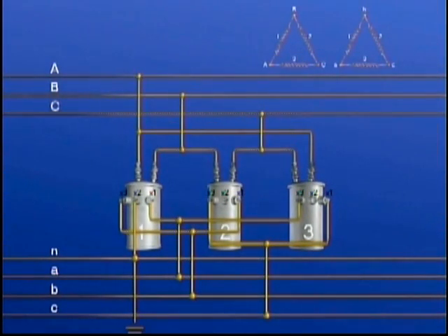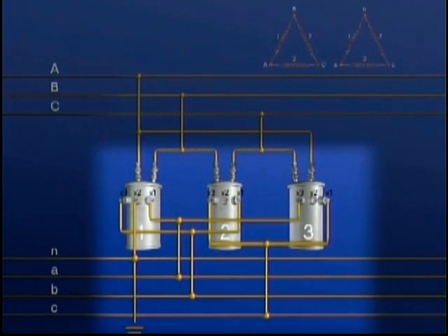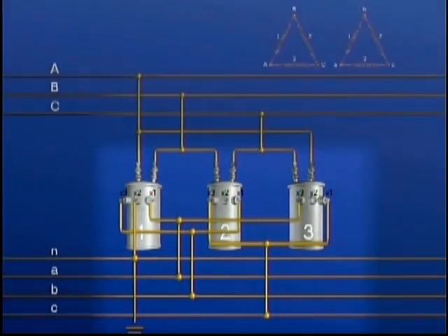Splitting the secondary winding on transformer number 1 effectively eliminates half of a winding on the delta connection between transformers number 1 and number 3 and produces the 208 volt power leg. Although not as efficient as a straight power bank, this type of connection allows you to provide single-phase and three-phase power from the same bank.